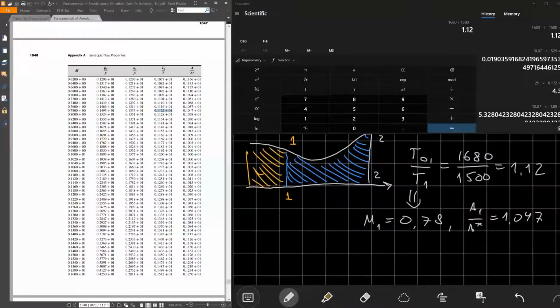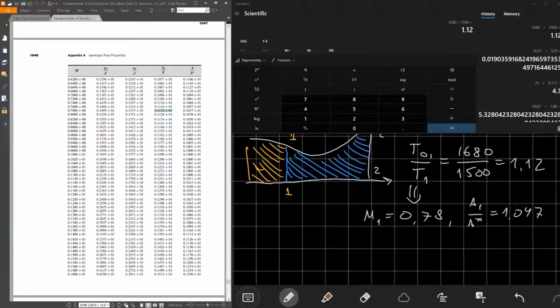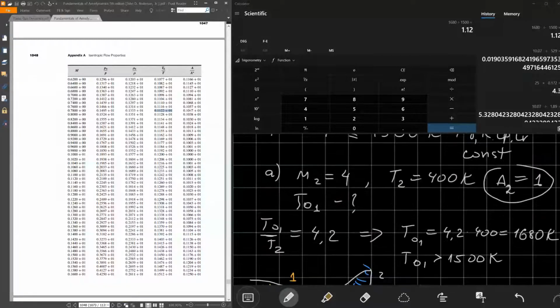Okay. So we can find where this area ratio is exactly, at which position, and we will see the coordinate at which this separation of two models can be used in one part of the nozzle. We will use non-constant gas constants there, and in the other, bigger section of the nozzle, constant values can already be used. So that was question 3.4.